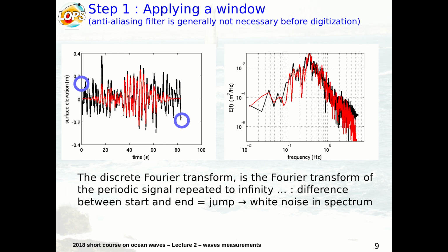When you apply a window, you try to make it equal at the beginning and at the end. This is to avoid this kind of problem. Yeah, I know that. Okay. That's the reason. Some windows actually don't go exactly to 0, like the Hamming window is not exactly 0, and it has better properties for the side lobes. And what's happening when you actually do this kind of processing, so you have an original signal and you change it by windowing, averaging, whatever.